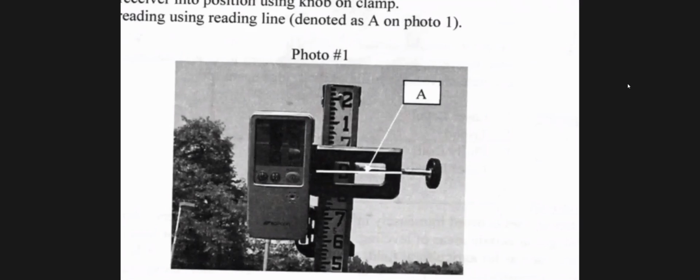So this instrument has arrows, and I'll draw these arrows on the whiteboard later. And you can visually see if the receiver is too high to read where the level point of the laser is pointing. And there's also arrows on the bottom that would point up. So the arrows on the top tell you to lower the receiver on the rod, or to raise the receiver on the rod. And there's also audio.